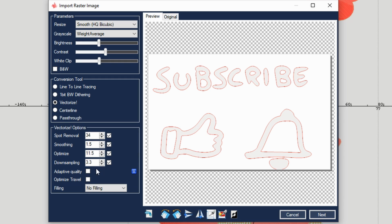Okay. And then we have also adaptive quality. This one will basically apply a certain quality depending on the size of the image. So if we are downsizing or upsizing the image, it will basically include more or less of the details available in the original image. Then travel optimization, again, this is something that happens in the background in the Gcode, and should produce a quicker job. And then you can also apply some filling.